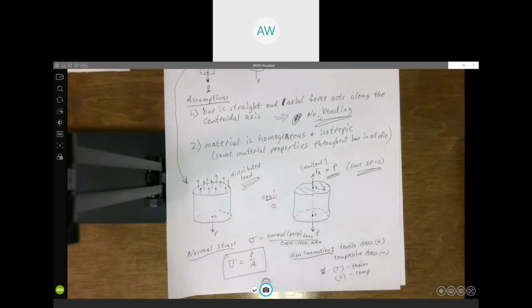But it is important to denote if it's a tensile stress or a compressive stress. And reasons being, to some extent, same thing it was in statics when you were looking at trusses. If the member is in compression, then you not only have to worry about the material failing due to the compressive stress, but you would also have to consider the possibility of buckling. That's when members in compression buckle, they bubble out. So that's one reason it's very important to differentiate between tension and compression.